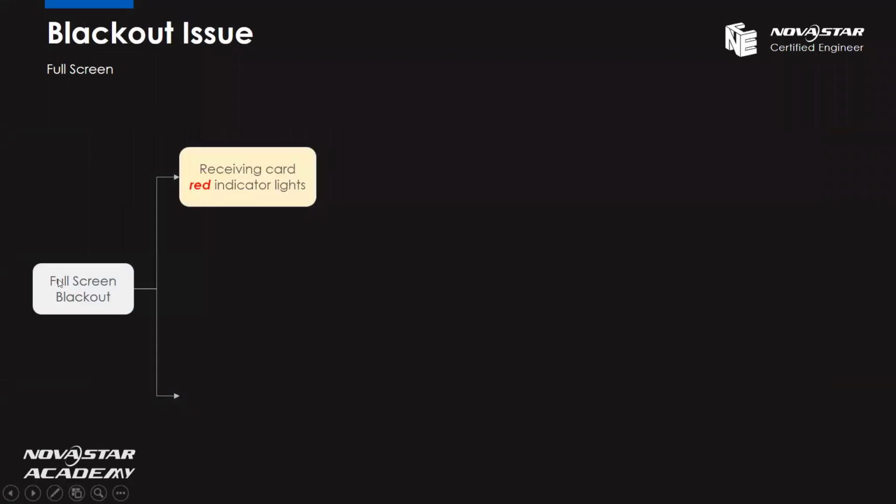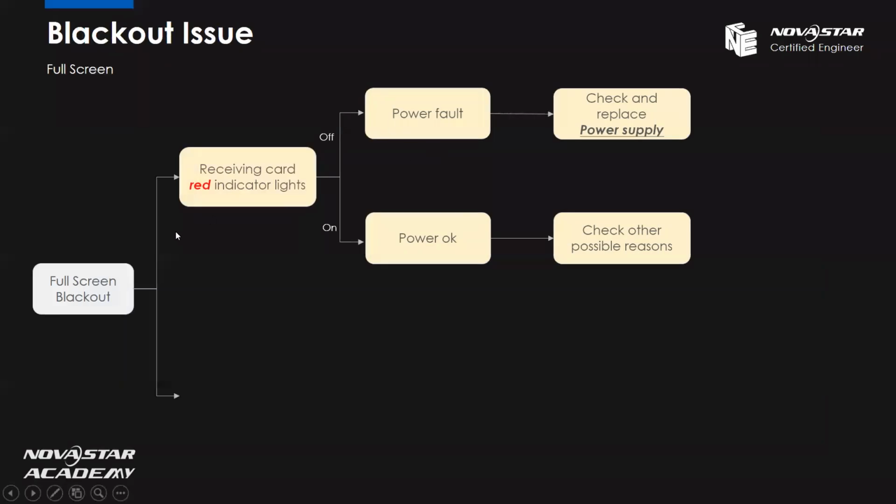So when the full screen blackout issues happen, we can make a preliminary judgment from the receiving card light. First, let's check the receiving card red indicator light. If the receiving card red indicator light is off, it means there is something wrong with the power. So in this case, we need to check and maybe replace the power supply.